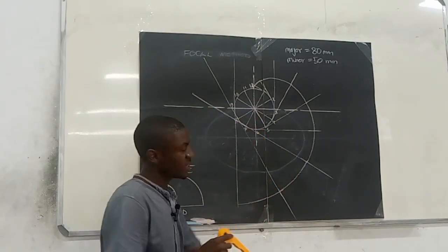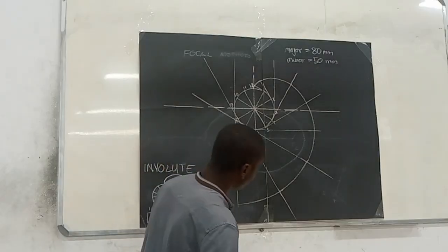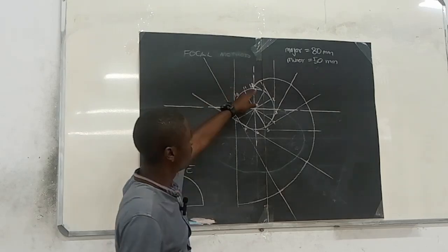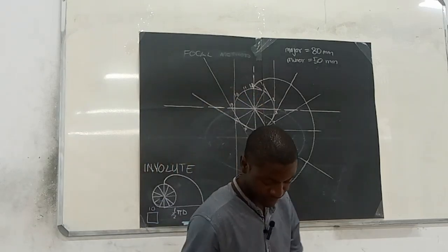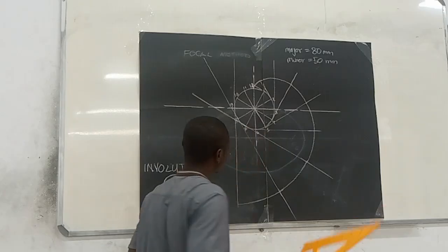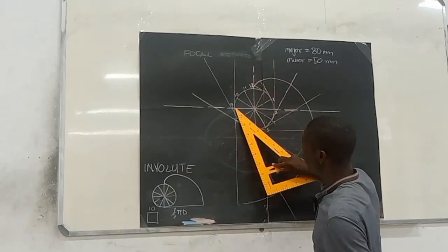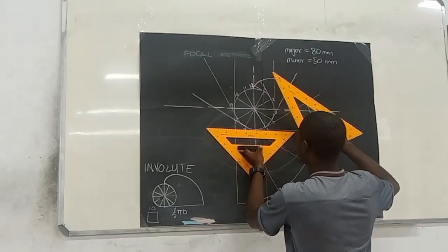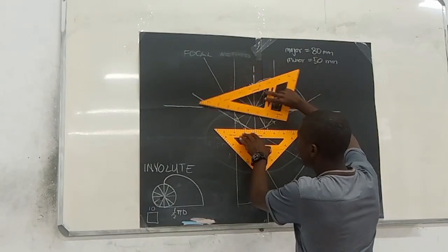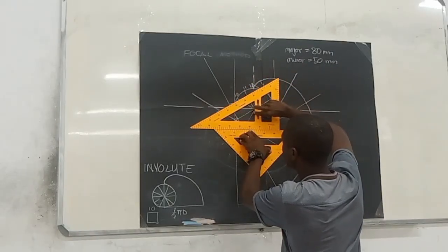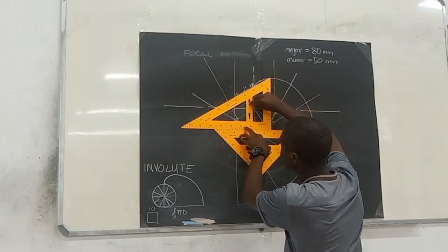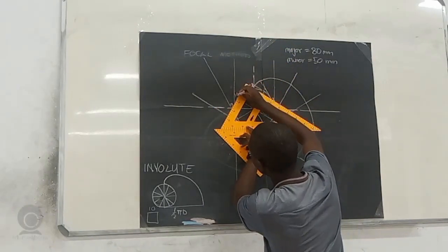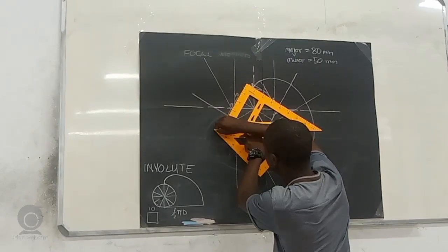So if you draw it too much at the bottom, you're not going to have enough space to draw everything. So I'll keep drawing until I have the point at 12. We have ended at 9, so I want 10. Just like I was explaining, you just need the t-square. So you place your t-square. You want the line to come this side. So you keep rotating. This is looking like it's at 90 at 11, but I want the one at 10. This is the point and the angle that I need, like that.